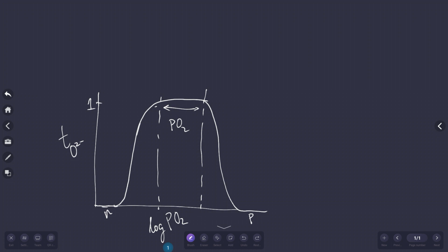If you're creating an electrochemical cell, or oxygen sensor or fuel cell, you use a stabilized zirconia membrane. The membrane will have to be 100% pure ionic. And your whole research will tell you what is the range where you can maintain that. Very, very useful for us. You know that if you want to use that material as an electrolyte in a device, make sure you do not cross this boundary.